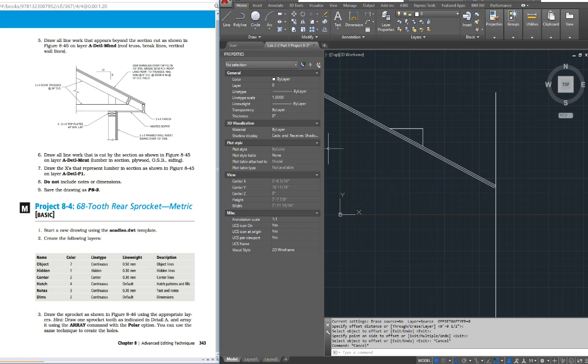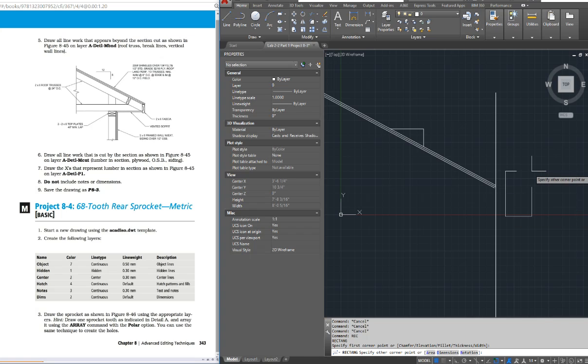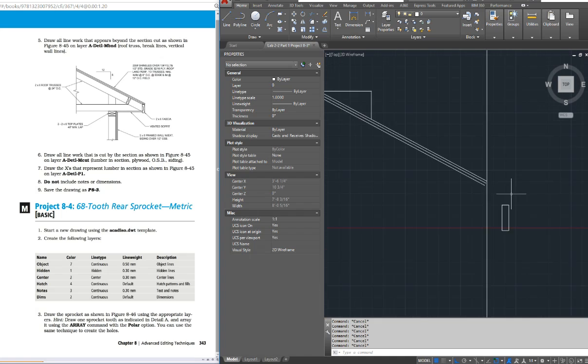Now you just need to look to see what it says it is. So here's a fascia, a 2x6 fascia. Those are uncut sizes. So I'm going to draw a rectangle that is 1.5 by 5.5. After they finish that board, after they clean that board up, it's cut down, we only get a 1.5-inch board for a 2x, and it's 6 inches tall, and we only get 5.5 inches. So I've drawn a 1.5 by 5.5 2x6 fascia board. And I need to put that in here.